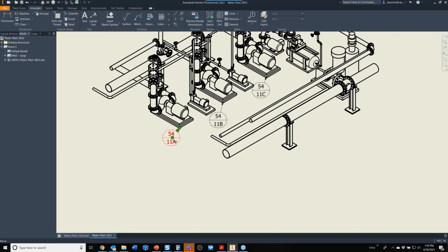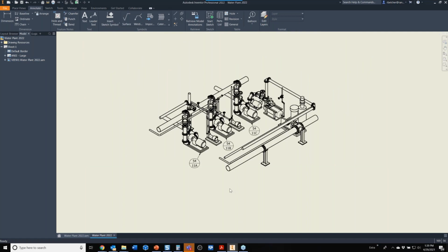Now I see each item with its common item number, but its separate, individual installation code. That functionality has been needed inside of Inventor for ages and ages. We've had it inside of the factory design utilities for quite a while, almost since the beginning of the factory utilities, but now it's part of the Inventor assembly environment on its own.